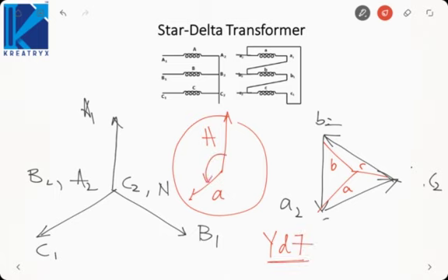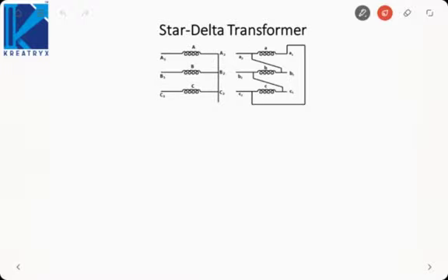And if we see, the phase shift is 150 degree anti-clockwise. So it is 150 degree lead. 150 degree anti-clockwise phase shift, that is 150 degree leading. Okay. So that is how you must determine the phase shift in any transformer. Let us change the secondary connection now.